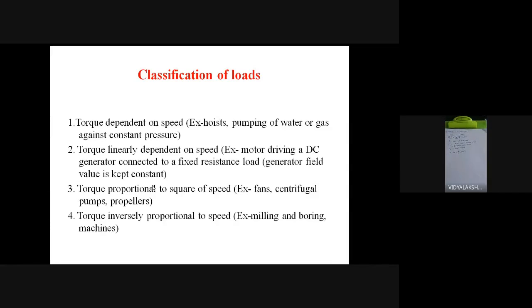Next step, I'm going to differentiate J omega m with respect to time. So I'll change it as J d omega m by dt plus omega m dJ by dt. I simply multiply J with d omega m, and then omega m, and then I differentiate the other term. Just the UV method.